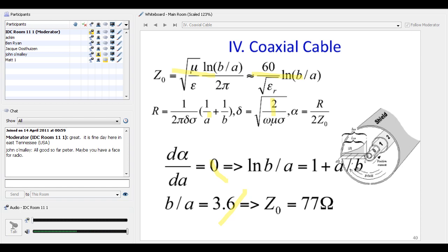He's long gone. So on the right-hand side, we're looking at this cross-section of the coax cable itself. The thing right in the middle, let's change the color, that's the center conductor. And then here's the shield on the outside. There's hot, there's not hot. And what this is showing is, if you change the materials, the dielectric constants, these things work differently.